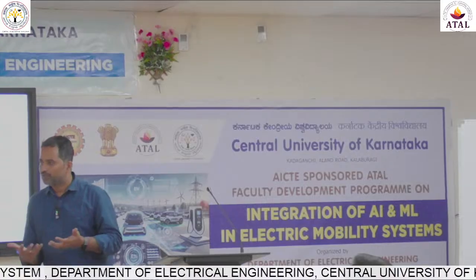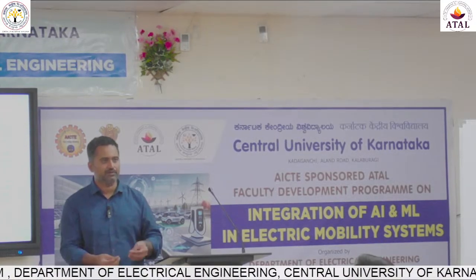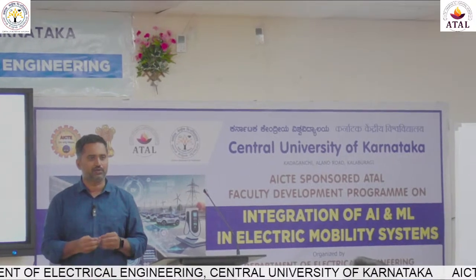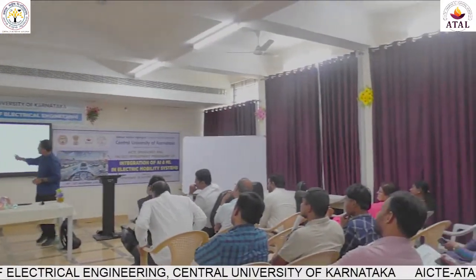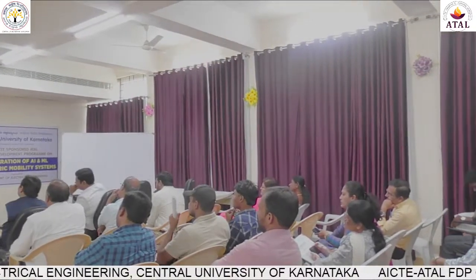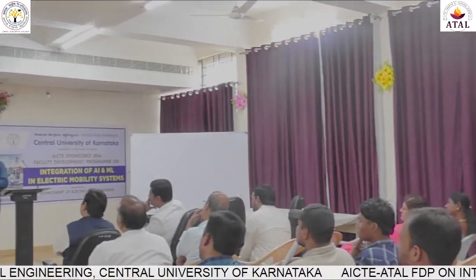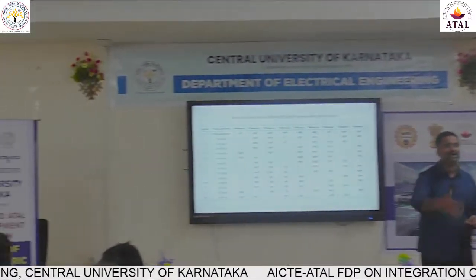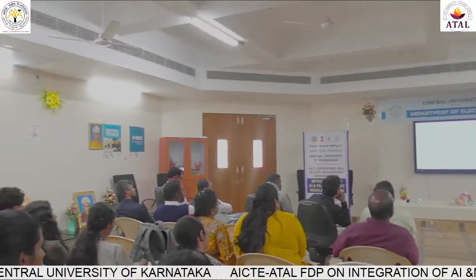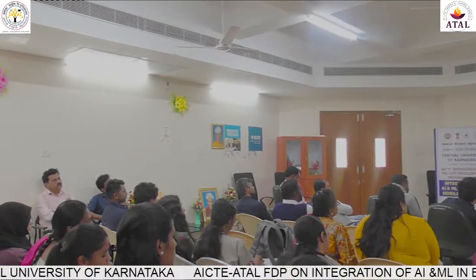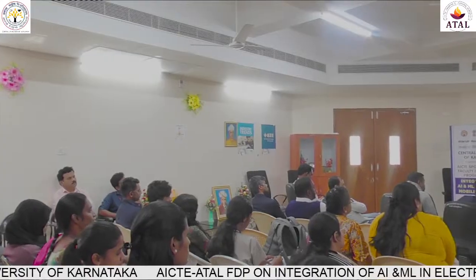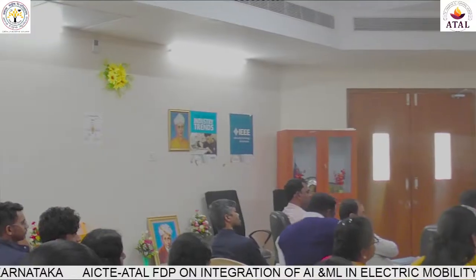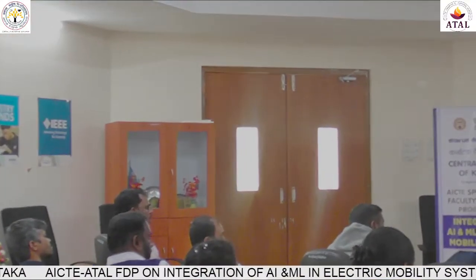So what I am saying is that we cannot escape; people have already started working on multi-phase, and on top of it there are a lot of other advantages I will try to bring in. So if it is only a 3-level and 9-phase system, you have this many combinations. Analyzing post-fault is fine, but how do you be ready to handle it at the time? What optimizations have to happen at the design level, starting from insulation to the kind of windings, to the kind of connections, to the inverter switches, and to the batteries?